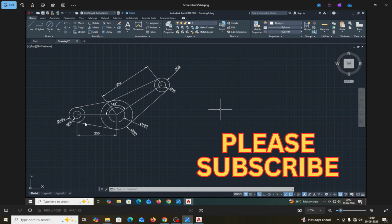There are these two lines at an angle of 144 degree. First, I will draw these two lines at an angle of 144 degree. Then later on I will draw the circles, 50 mm dia and 100 mm dia. Now start. The distance is 250 and this distance is 350 and the angle between them is 144. First I will make these two lines.